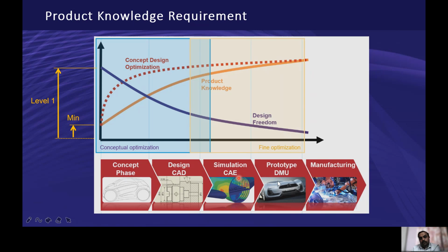Then it goes to prototyping. It's not compulsory that you have to do prototyping, but whenever you feel there's a criticality in terms of manufacturing or in terms of fitment, or if you're not sure about its functional responses, then you might develop a prototype, or you can also do it on a digital mockup in CATIA.